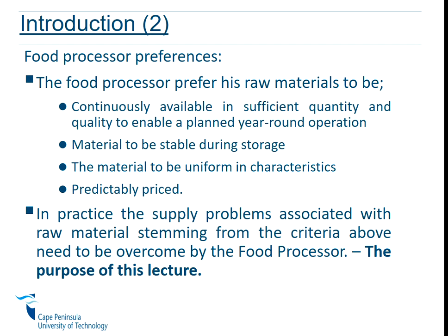And most importantly, you also want the materials that you're purchasing to be stable during storage. So in some cases, you may purchase stuff, let's say, for example, in January, but you're going to start processing or you're going to start using that in March. So you want these raw materials, when you are storing them, to be stable. You don't want to store a raw material, then you find out at a later stage, there's mold growth or there's microbial growth, or maybe the protein has decreased, or maybe the starch has decreased. You want your material to be the same.